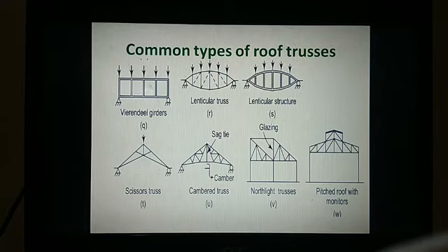Coming to the applications for long spans, even airport hangars to maintain aeroplanes, which is something like an aeroplane shed, where they nowadays use PEB structures. No one is using these kind of regular trusses nowadays. Why? Because you require a lot of bracing systems for these roof trusses. That is the reason they are going for unbraced portal frames, which need no bracing systems within the chord members. That is the reason nowadays people are going with more economical and more lightweight structures.